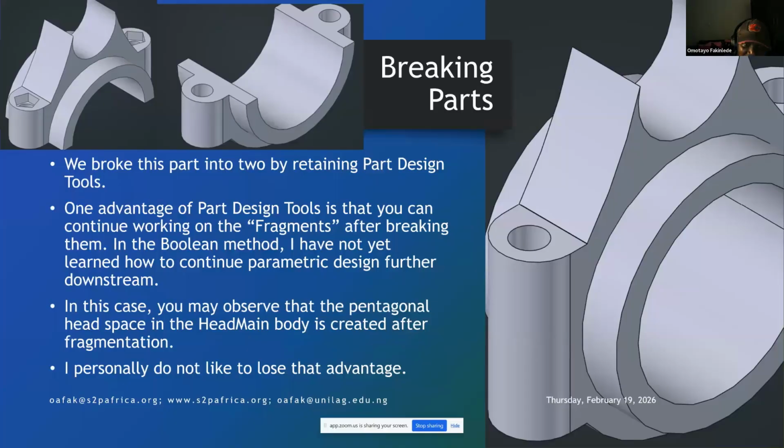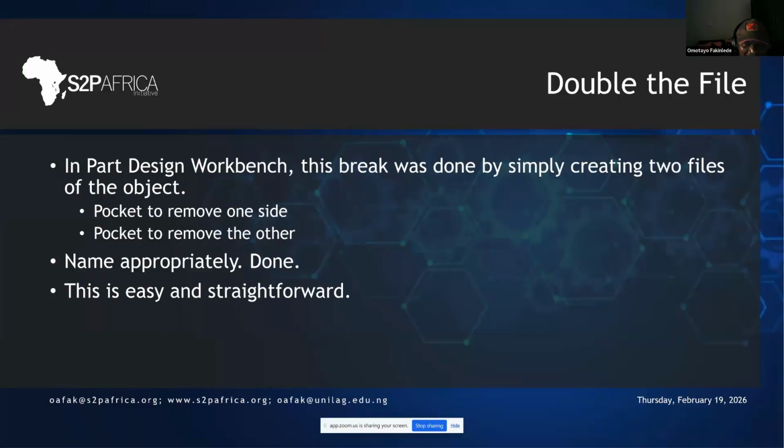That is a preference. In the Part Design workbench, this break was done by simply creating two copies of the object, pocket to remove one side, pocket to remove the other, name appropriately, and it's done. It is easy and straightforward, and I encourage you to try it out.